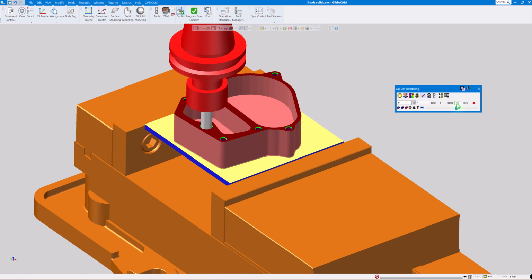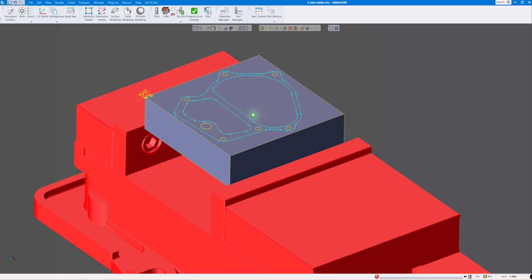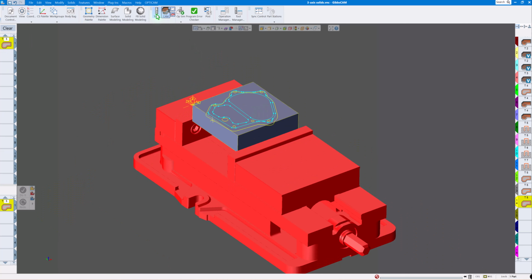And 3/8 hole. Now if I look at my operation list there, my chamfer tool is tool number 5, which is the spot drill chamfer tool. So you can see I'm doing tool number 5 to spot. Then I'm going to use tool number 5 to do chamfers there.